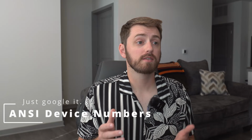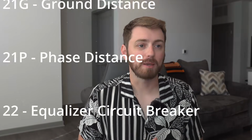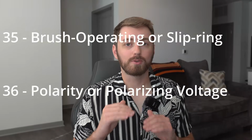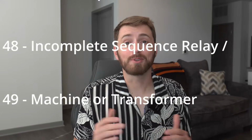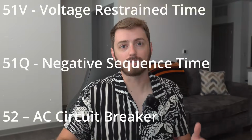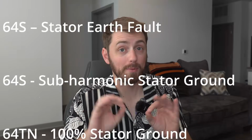In most relays, each protection function can be called out by its ANSI device code. This is just an arbitrary 2-digit number that represents a function or a device defined by ANSI and IEEE. I'll scroll the list on screen so you can see them all. There's also a link to the Wikipedia page in the video description as well. Honestly, I've been doing this for 12 years. I don't remember them all. I have to look this article up all the time to remember what's a 67, you know, what's this, what's that, what's a 47. Don't stress out about memorizing all of them.